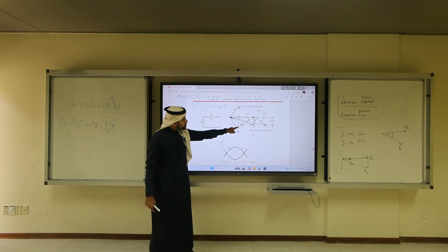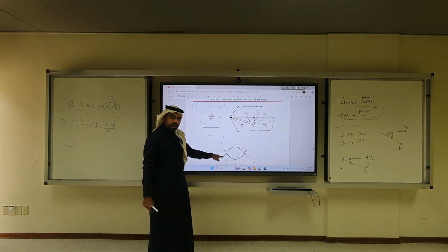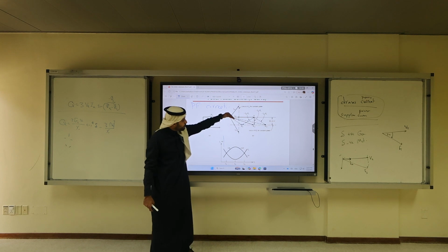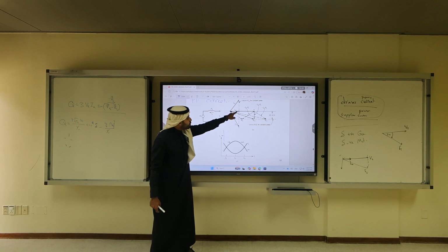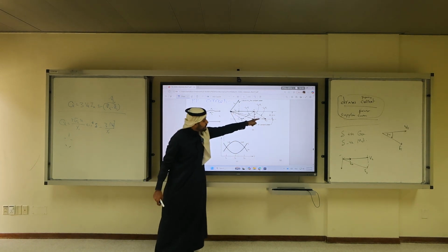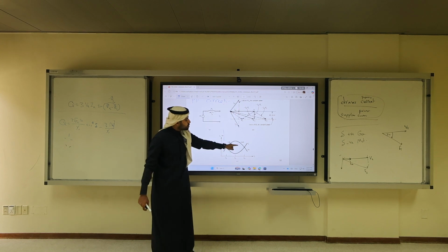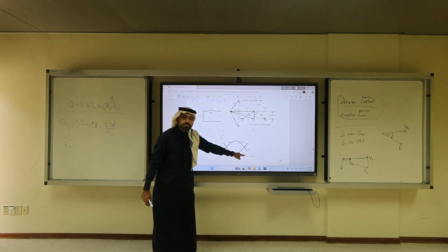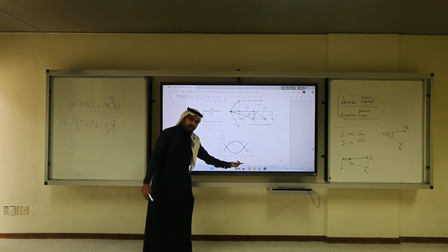For IF1, which corresponds to EF1, I have a larger magnitude of IA, but my power factor is lagging, far from unity. If I have IF2, I'm going to have the smallest magnitude of IA, but I'm going to have a unity power factor. If I have EF3, the armature current goes back higher in magnitude and the power factor is leading. So the V curve is basically the IA versus EF or IF relationship.